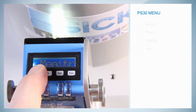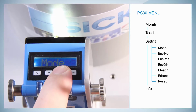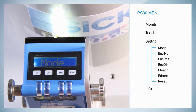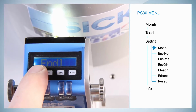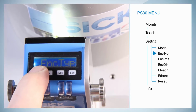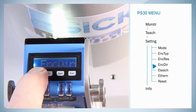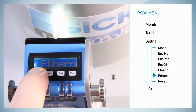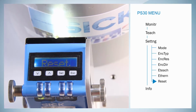The next item which is presented is the setting menu. In this menu, the different parameters of the sensor can be modified, such as mode, which allows a switch between single object and endless mode. The 3 menu items encoder type, encoder resolution, and encoder direction allow the modification of the first installation settings. Further menu items are the settings for the external teach as well as the Ethernet configuration. By reset, the sensor can be set into factory settings.